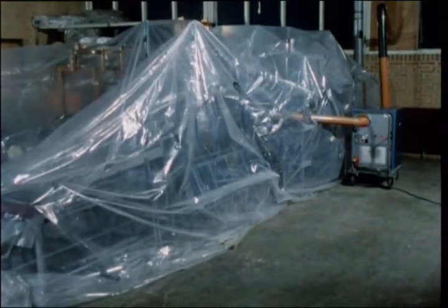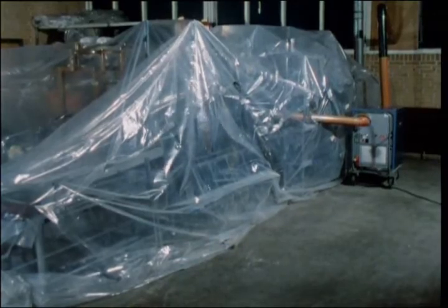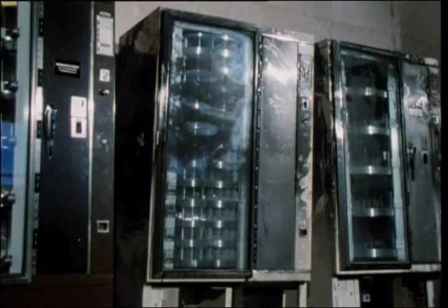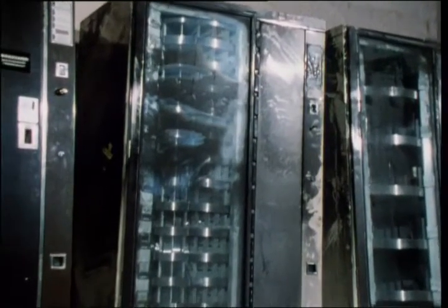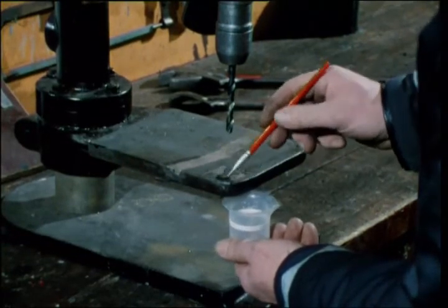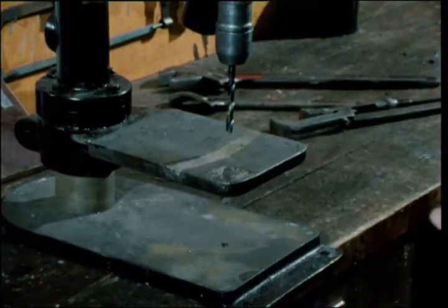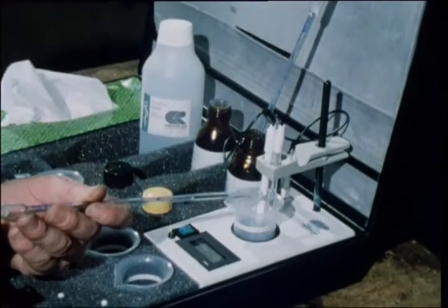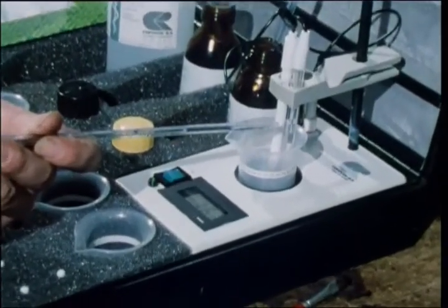But intensive corrosion will come from the acid formed when the water dissolves the products of combustion of the plastics used in modern building. 1 kilogram of PVC burned in air gives a litre of concentrated hydrochloric acid. So chlorides are estimated by taking a sample and titrating on portable equipment. All chlorides must be removed.